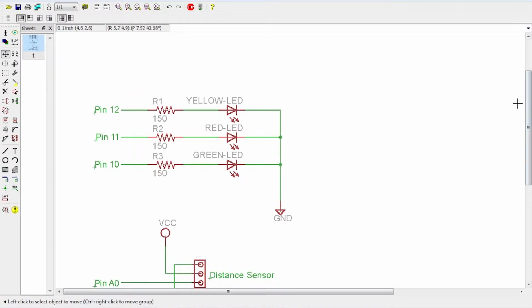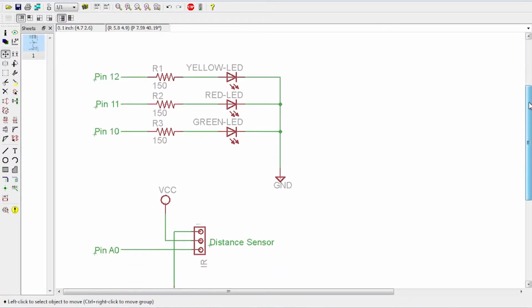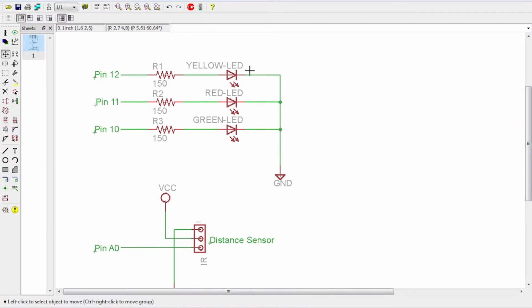So let's use a switch input into the circuit to do something interesting and make a kind of mood color LED chooser that you control with your hands. Here's what we'll need to accomplish this. First off, we'll have 3 different colored LEDs. You can choose whatever color you want. I chose yellow, red, and green. These should be connected to 3 PWM enabled pins in the Arduino so we can change their brightness. Each one will have a current limiting resistor of 150 ohms as we usually do.